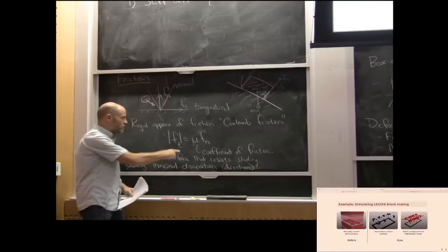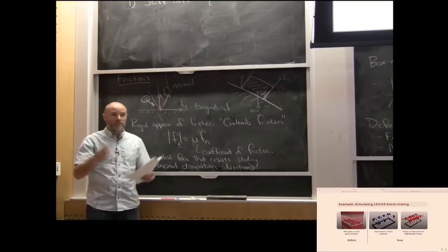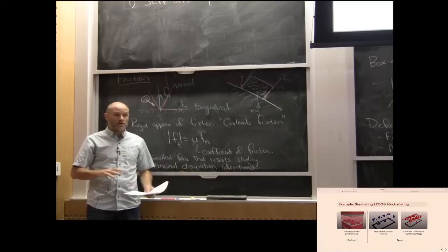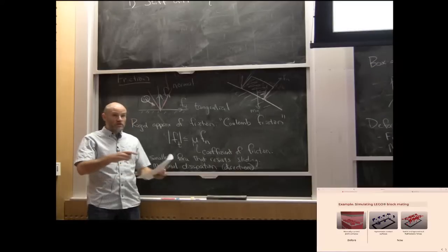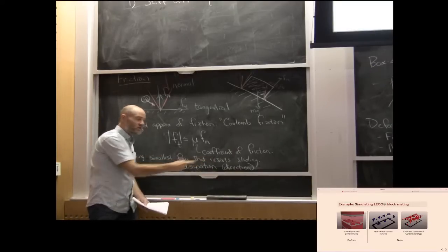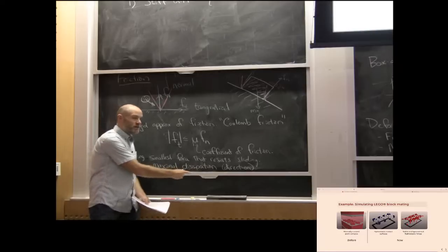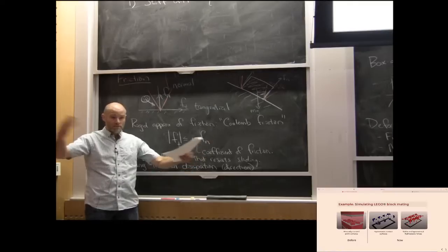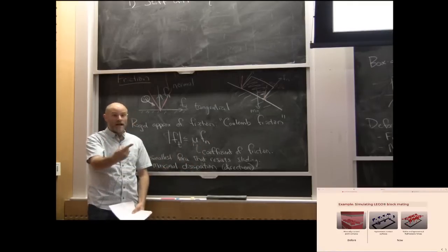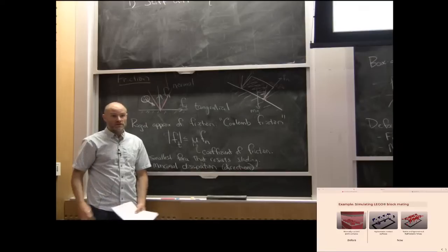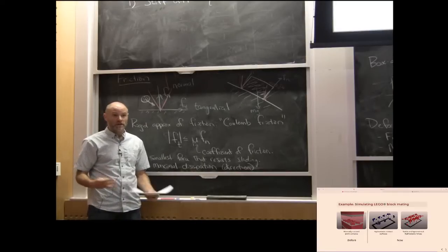The interesting part is when I'm doing rigid contact and trying to avoid penetration in a multi-body setting. Then you resolve these forces, with smallest force that resists sliding and maximum dissipation, in the multi-body equations with all of them adding constraints, and you solve an optimization problem in every time step to resolve the forces. These are the time-stepping simulators.